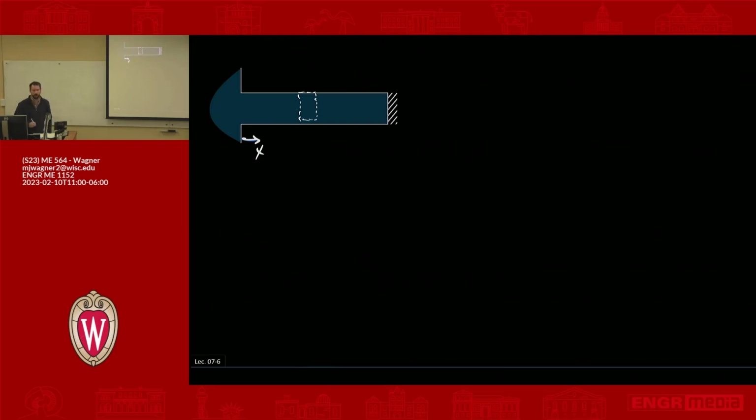And I'm going to now keep track of all the stuff that's going in and leaving. Sorry, this control volume extends down, right? So coming in the x direction, we have q dot x. Leaving, we have q dot at x plus dx. And then we also now have convection, right? This is different from what we've done before. We had generation in the last set of problems. We don't in this problem. We have convection away. So let's just draw it leaving.